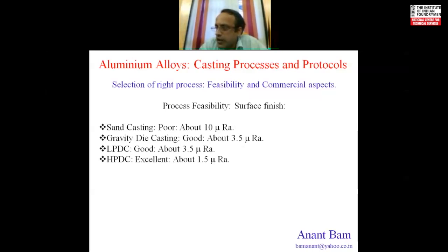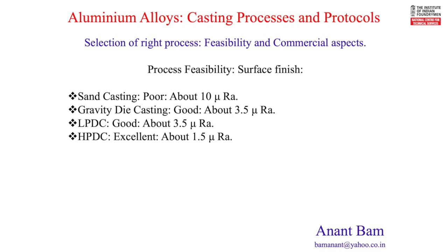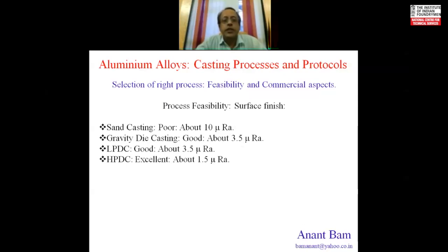Commercial coatings like number 140, number 21, number 39, etc. These coatings are to be touched up after every 3, 4, at the most 5 shots, thereby losing the tandem or rhythm of the cycle. Advanced coatings like 1400, 3600 or any further coatings are designed to last long. And if properly applied, these coatings can last for as long as 3000, 4000 shots. Every coating has its own application and its own effect. Since that is not the topic for today's discussion, we will skip it and straight away move to HPDC coatings.